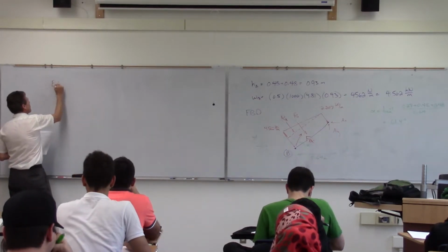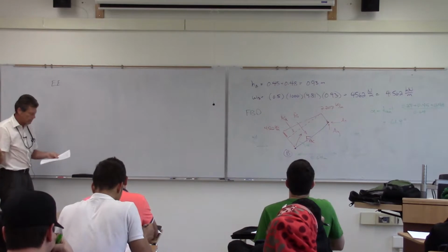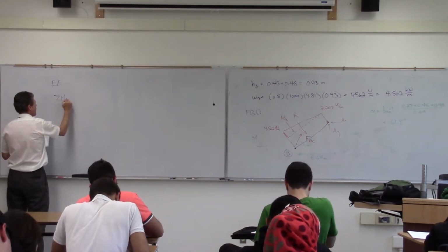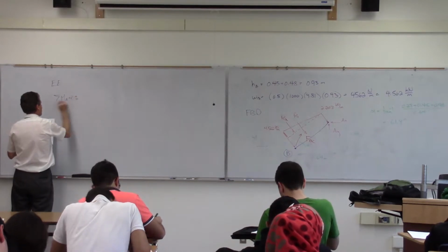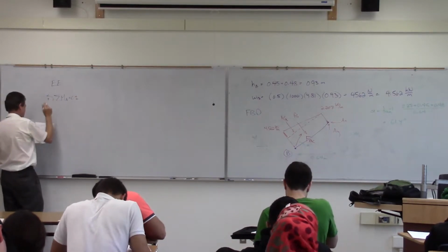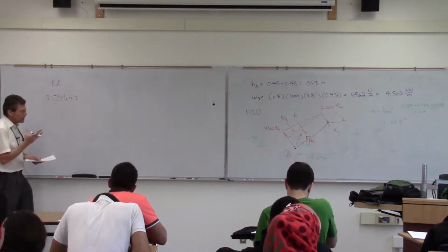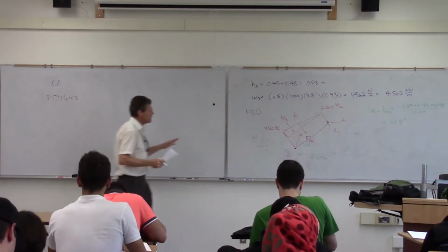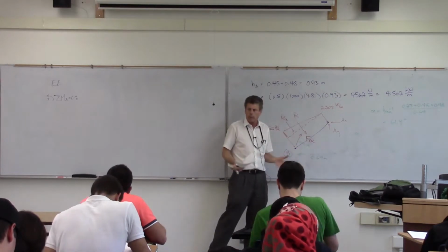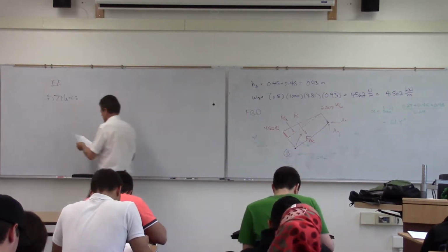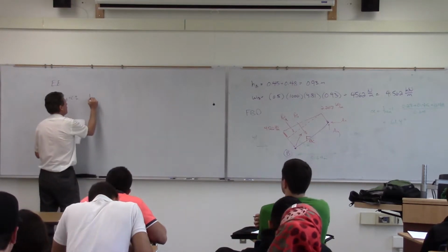Okay, so I've drawn my free body diagram. The next piece is my equilibrium equations. Pick a direction in terms of what I want to consider positive. And again, the nice thing about what we're going to find about fluids is since they act perpendicular, distances are already measured perpendicular, basically. So it's going to be rather simple.